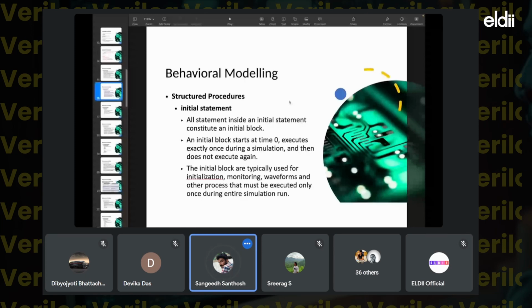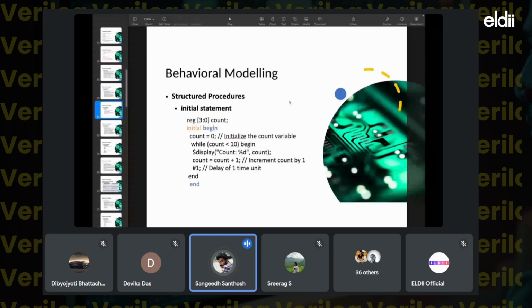The next thing that we will be using in design statements: for every output in design, we are going to use registers in behavioral modeling. In all the other modeling, we just represent it as output y, output s, comma c. Now, in behavioral modeling, we represent it as output reg y, output reg s, comma c, because that particular value needs to be stored, since it depends upon the previous input also. So we are going to use registers in behavioral modeling.